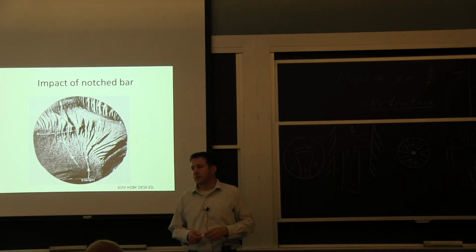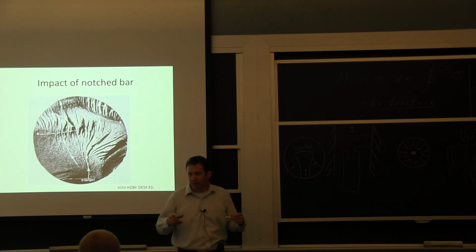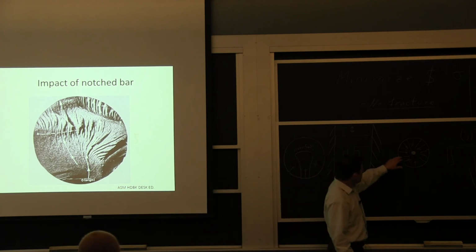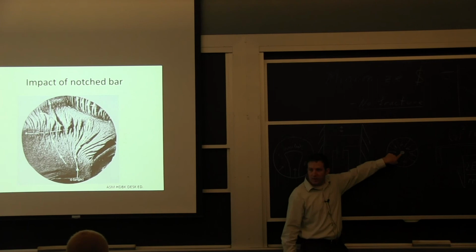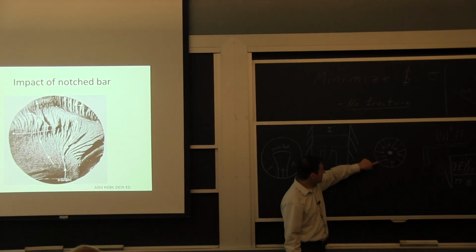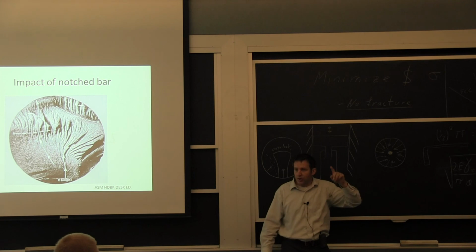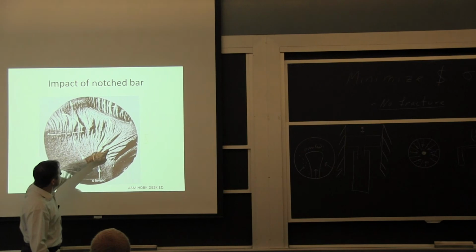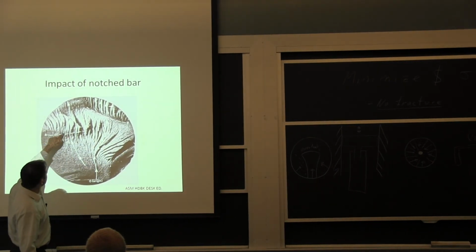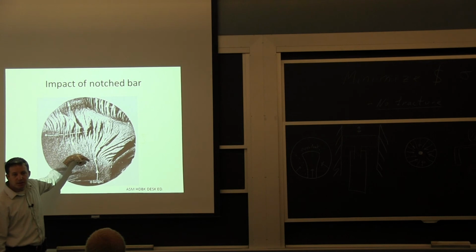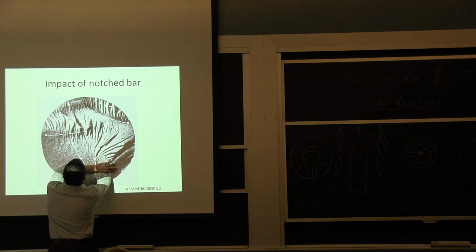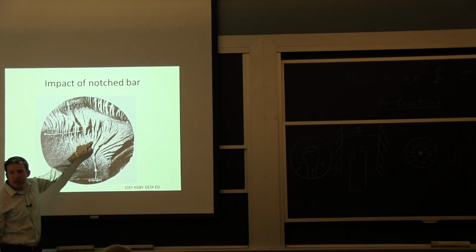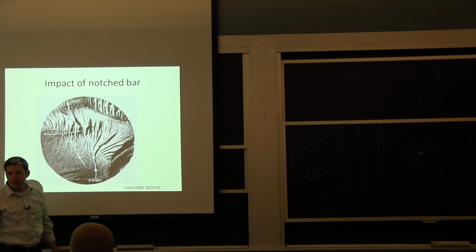Yes? So you work backward to determine the origin. That was the question. You have to look at the two types of lines. You have the crack arrest lines and you have the crack propagation lines, and they will point you to one origin or multiple origins. So in this example, if we look at these crack propagation lines right here, they all point in this direction. So that's where it started. Even if I didn't know this and I'm looking at this, I know it didn't start this way because it was spreading away from that area. So you have to look at the spreading, essentially.